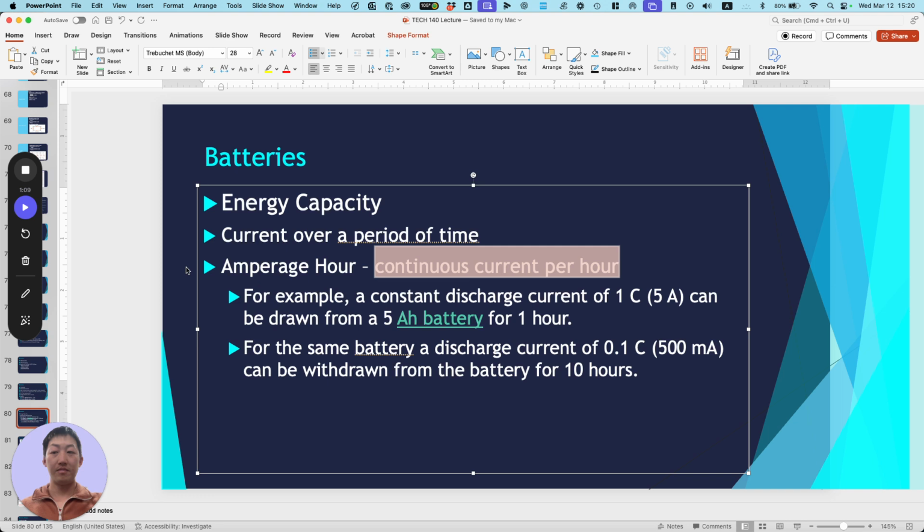Okay, so yeah, it's valid to think that the battery also goes to the flight control board, but you can see right here, these are going to go to your motors. You can also generally tell this is going to be the ESC because it doesn't really have any fancy chips on it. This type of chip is more like a processing chip.